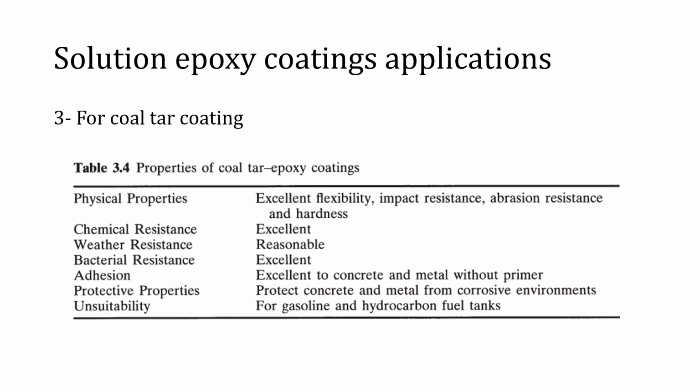Epoxy systems have also been used for coal tar coating, which consists of three main components: pitch, epoxy resin base, and curatives. In these systems, both liquid and solid epoxy resins can be used as the base, and various curatives can be employed for the coating formulations, including amines, amine adducts, and polyamides.